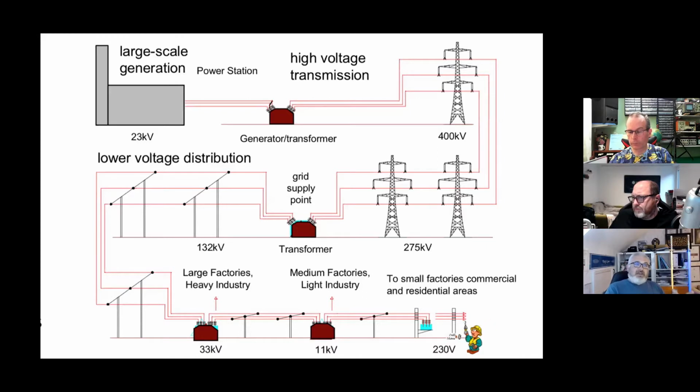And then from 11 kV subs in the local communities, you get your 400 volt feeders, or branches as they call them, going out with T's off of each phase into residential properties. And that's where your electricians kick in, whether it's three phase or single phase. So I thought I'd throw that little piece of knowledge in.